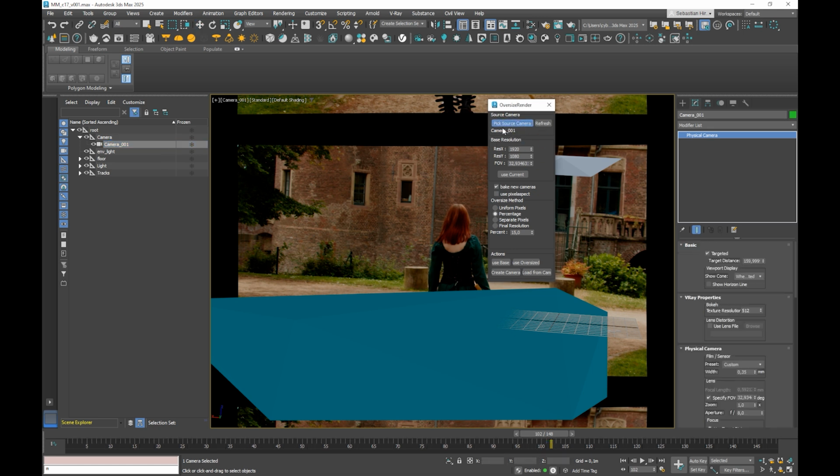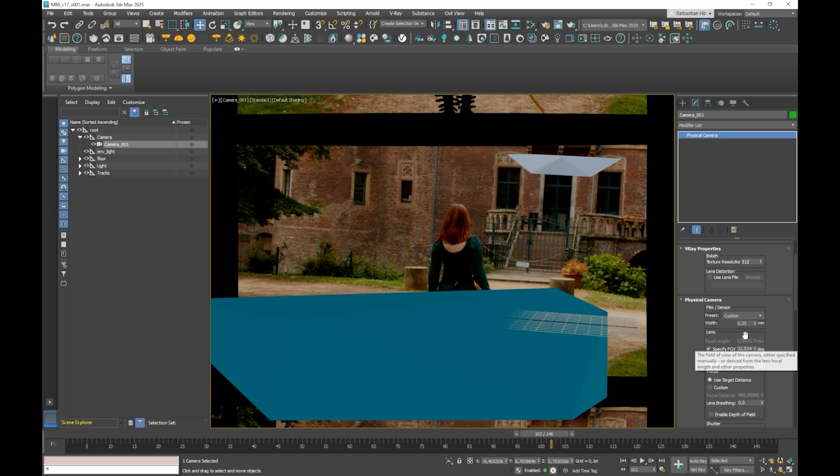If it's not already picked, you can pick the source camera here. And then you do the math. You add the 15% here. And this is the current settings. And by the way, before we do that, you'll notice that there is a little discrepancy here. For some reason, Blender exported this all wrong by the factor 100.